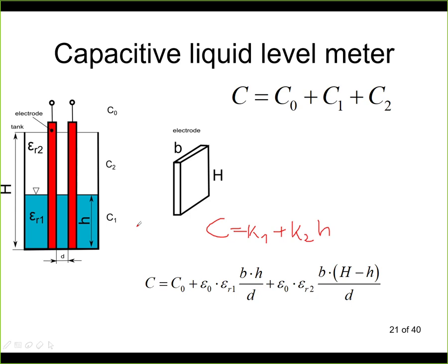It will probably not work with water. Distilled water will work fine, but normal tap water will not work because it's slightly conductive. So the recommendation is that you should always insulate at least one electrode, at least if you don't know what the electrical properties of your liquid are.